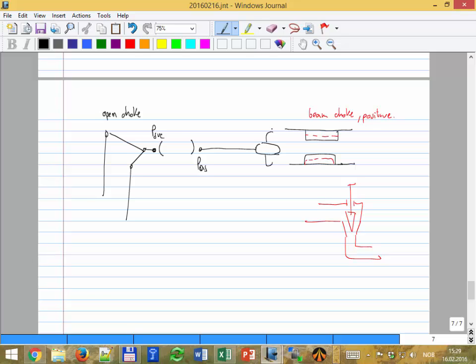So what will be a strategy? I propose to do countercurrent calculations from here to here. With the given rate, I have the total rate of the system. With the given rate, I have separator pressure, and then I can calculate pressure at the discharge of the compressor. That's nice, no issue. Now what happens here? I know that the total rate is Qt, but how do I calculate the pressure at the suction of the compressor?